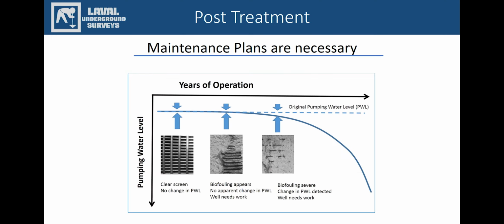Putting together a maintenance plan is necessary for keeping pumps and water wells functioning correctly. The phrase, failing to plan is a plan to fail, rings true here. If a plan isn't implemented to continuously check and clean a well over a period of time, there will be buildup and corrosion that's likely to come. It will be costly and it will be difficult to remove because of the stratification layers that occur when the deposits are left after a long period of time.